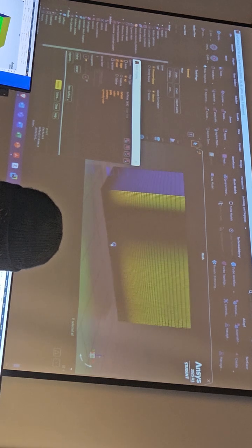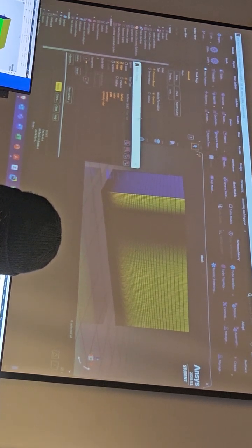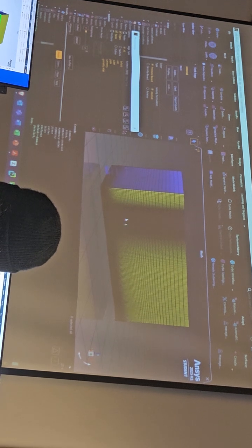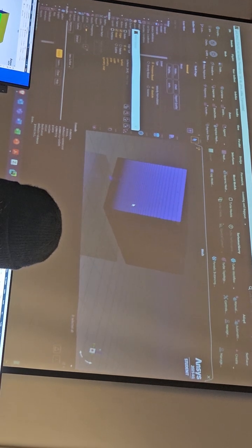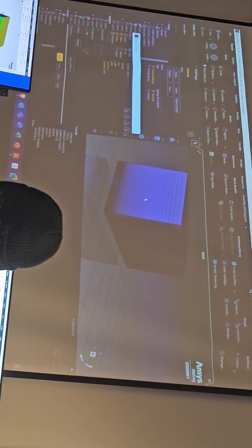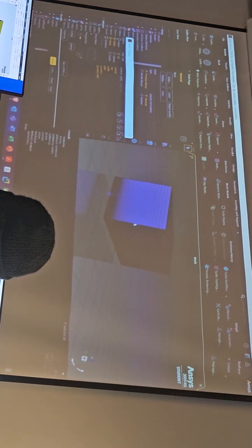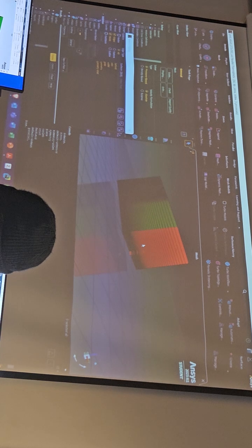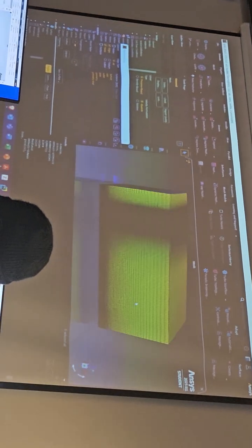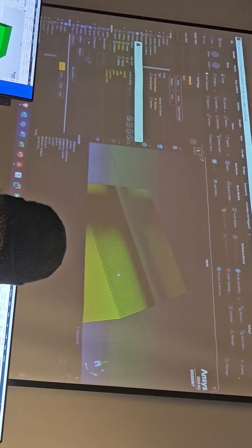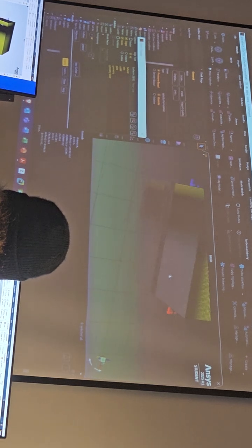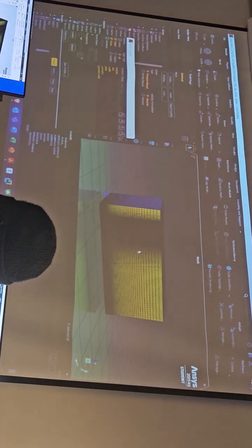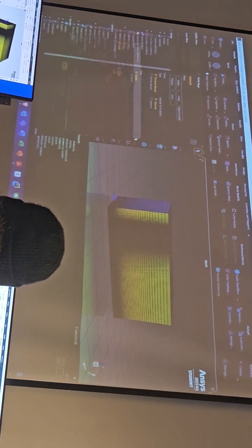You can also see that every surface has a different color depending on the actual boundary condition that is set. Well, I'm colorblind, so I don't trust the colors that I say, but this is somewhat blue. Then here, this is the inlet, the outlet is red. Then here we have some yellow, these are the symmetries. And then there is this gray, this is the wall. So you can already check what the boundary conditions are there.